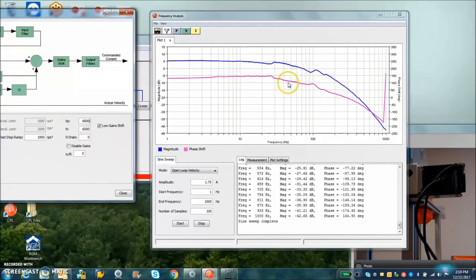And we got some phase shift here. I guess it starts at about 180 and flips over around 0 here. So the gain is less than 0 at this point, so we have stability. But we're probably getting a little bit of integrator windup there. I pushed the integral on it to flatten it out, but there's a zero that extends the velocity. So I'm going to cut that down a little bit, and maybe let's try a notch at this frequency here and see if we can notch it out.